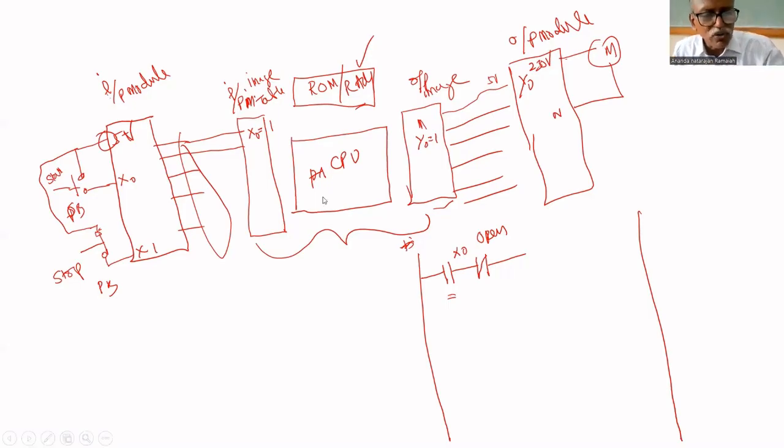That's why what I will do is I will put normally open again. It means this is always closed. The stop button is always closed. That's why this is also 1. Am I correct or not? Have you understood this point? Because it is always 1, the stop button is always closed. That's why this is also 1. 5 volt is available on the other end.